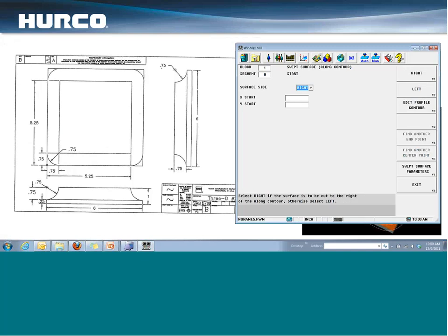Usually, wherever you put your 0 point of your profile contour, that's usually the contour that you want to choose for your along contour as well. It doesn't necessarily always have to be, but it makes working with swept surface a little easier. So since I defined the start point of this arc, and that'll be riding around this point on the along contour, that's the geometry I'm going to choose for my along contour.